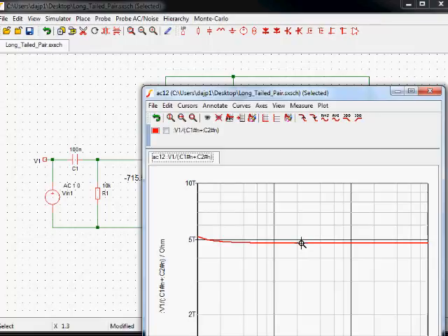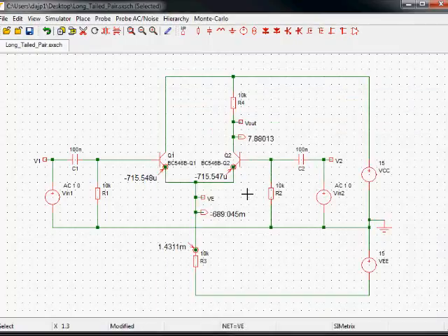Is that right? No, it's not. While Simetrix is quite good at deciding that impedances must be positive, therefore not worrying about whether you type hash N or hash P for the current through a capacitor, if you add up two currents through two capacitors, then it's a bit more important to get it right.